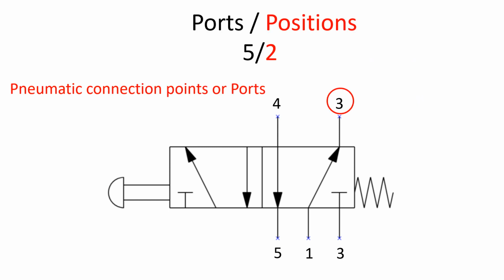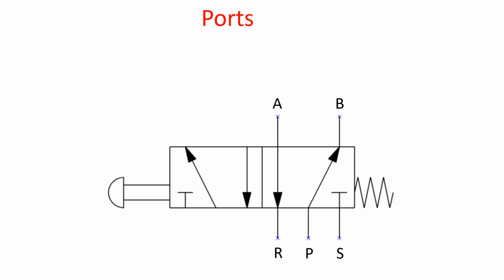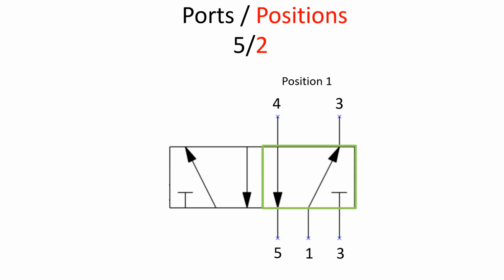How many connection points will I need? Before we continue, it's important to remember that some manufacturers use numbers to identify ports and connection points, and some manufacturers use letters. Refer to the component's data sheet for details. The next bit of information is how many positions does the valve have?